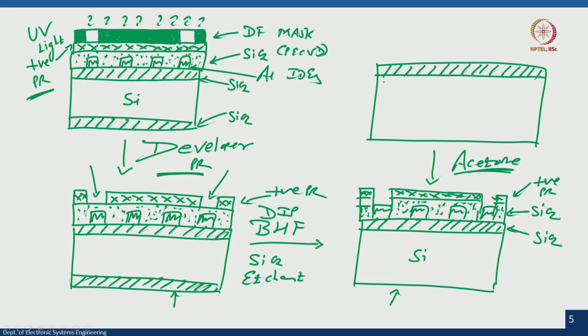So, it will get etched in the buffer hydrofluoric acid. What will I have? I will have my contact pads open, right, and other area is not open.